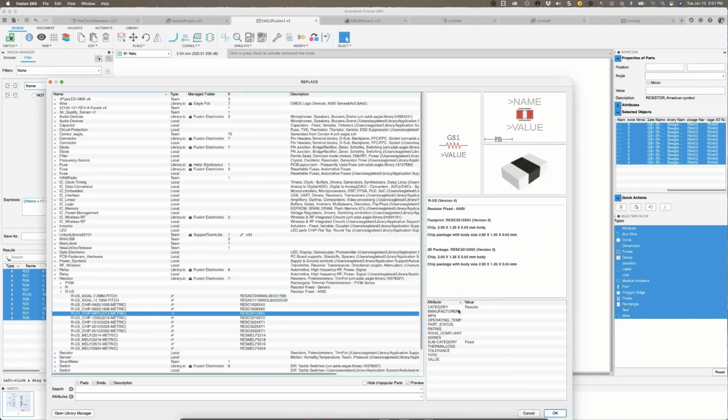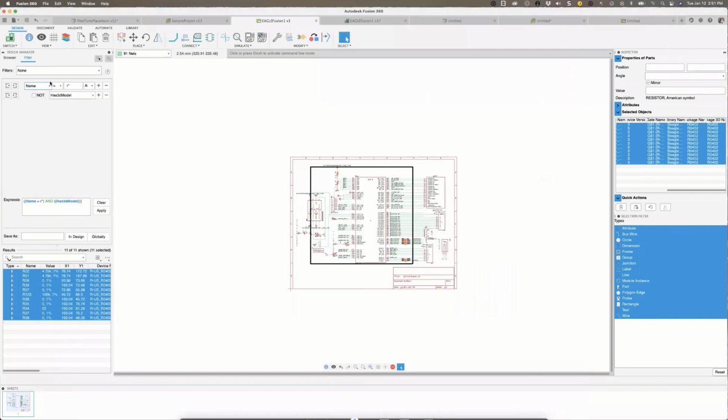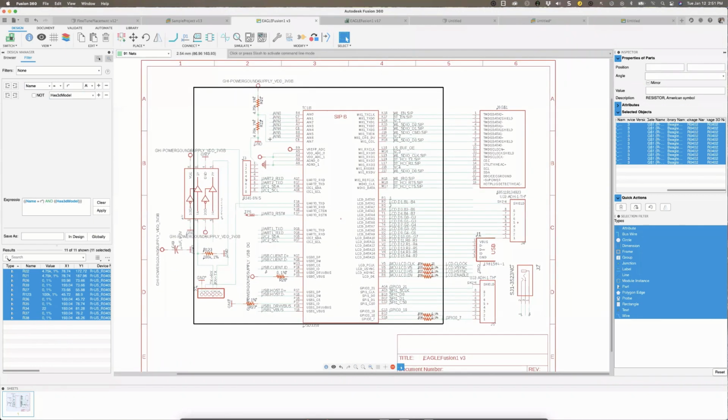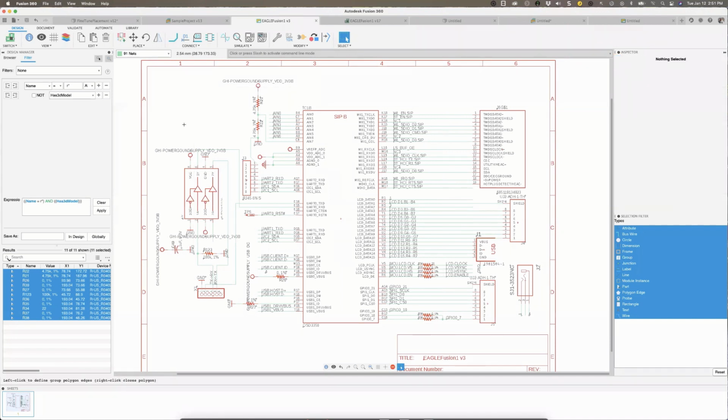Okay, so I could easily just select all the components and go to the inspector and tell it I want to swap out which footprint I wish to use. Extremely convenient. So with only a few clicks, you're able to change all of your footprints from one format to another format. Useful, let's say you want to go from 0402s to 0805s, or you want to go from surface mount to through hole and so forth. And you don't want to do one at a time.